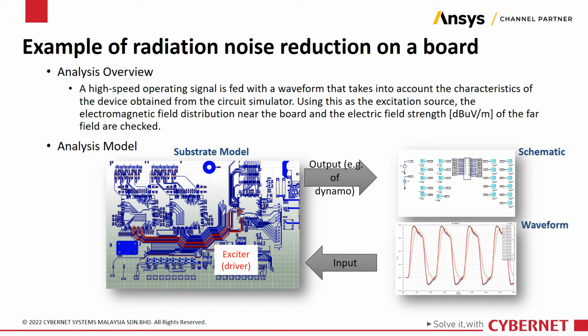This is an example of waveform signal analysis using Ansys SI-Wave. The wiring shown in red on the left side image is the target of the analysis. First, the entire PCB is analyzed by electromagnetic field analysis, and then circuit analysis is performed automatically. The IC at the center of the upper right image is the S-parameter model of the specified wiring, and the IBIS model is placed on the left and right. The result of the analysis is the waveform in the lower right image.